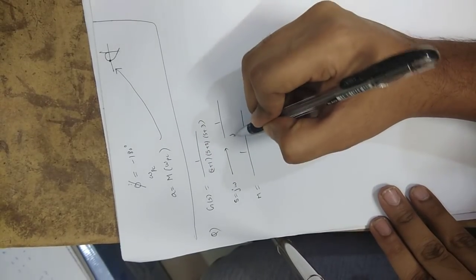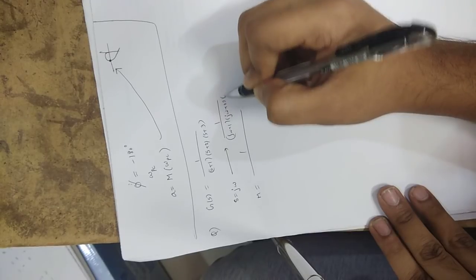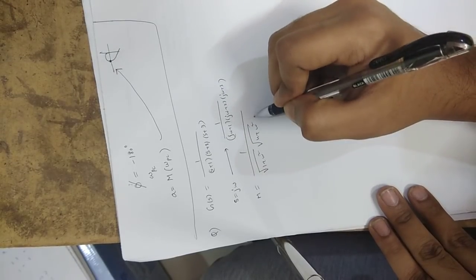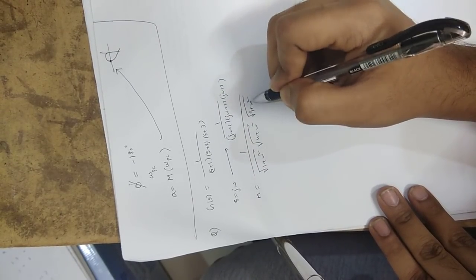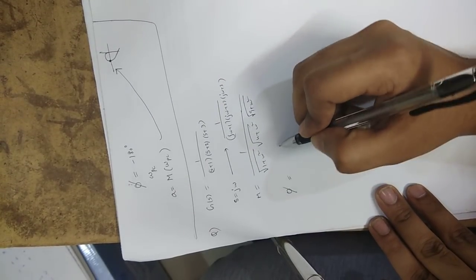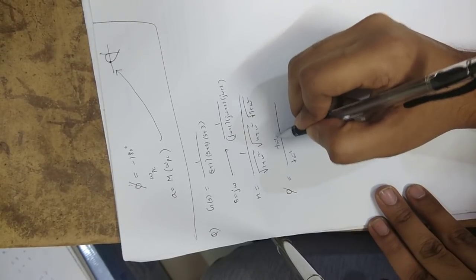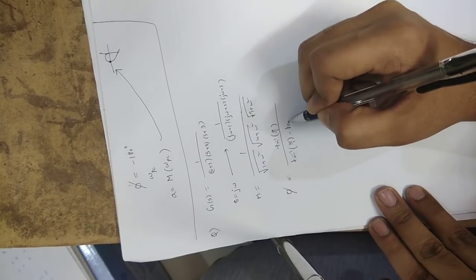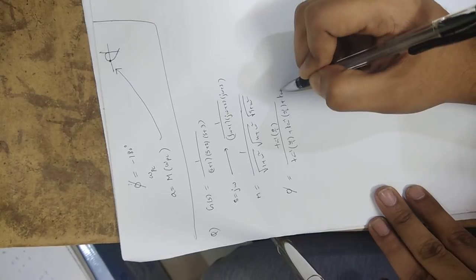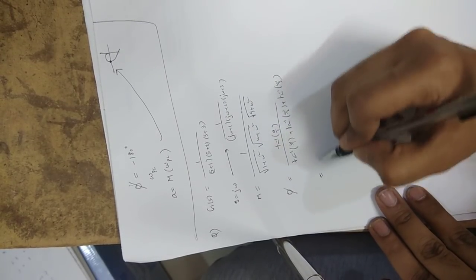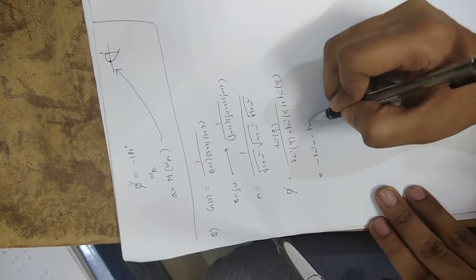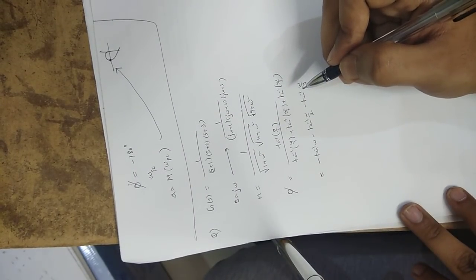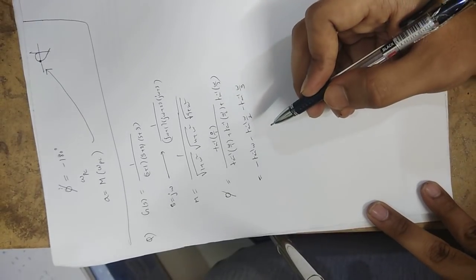Putting s equal to j omega, we get (j omega plus 1), (j omega plus 2), (j omega plus 3), and the magnitude is 1 by root of (1 plus omega square), (4 plus omega square), (9 plus omega square). Okay, phase. What is the phase? 1 by, this is tan inverse 0 by 1, here tan inverse omega by 1, here tan inverse omega by 2, here tan inverse omega by 3. That is, phi is equal to minus tan inverse omega minus tan inverse omega by 2 minus tan inverse omega by 3. So now we got magnitude, we got phase.